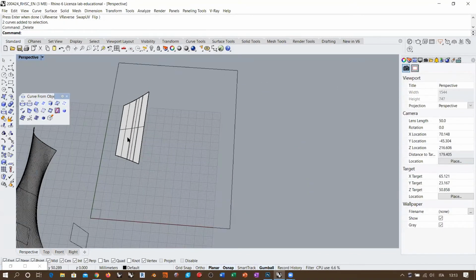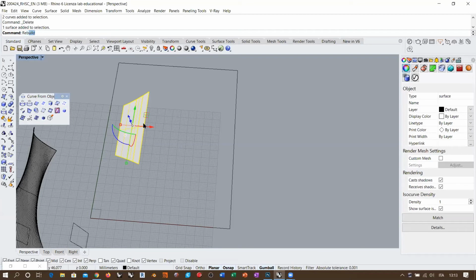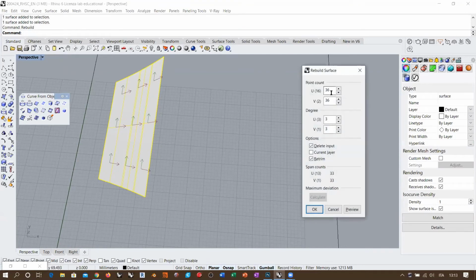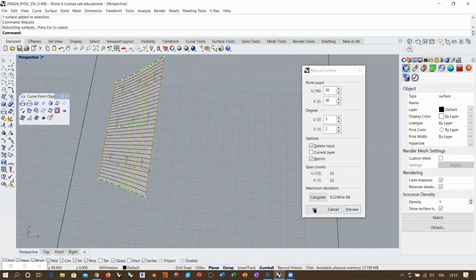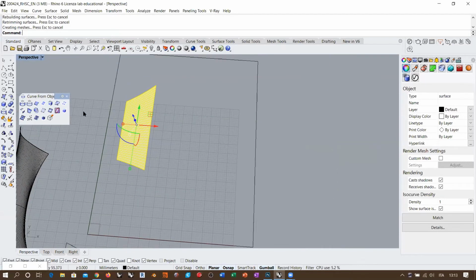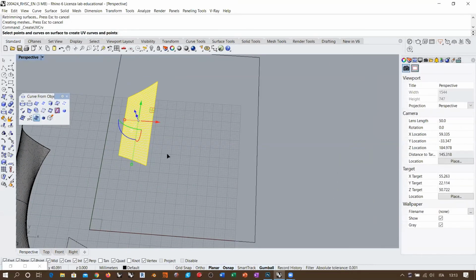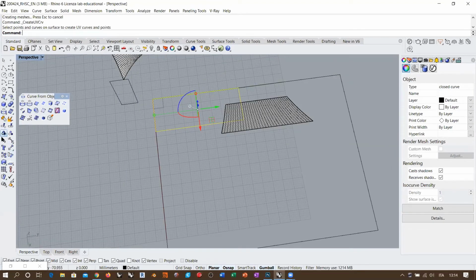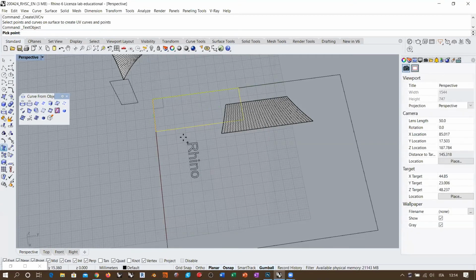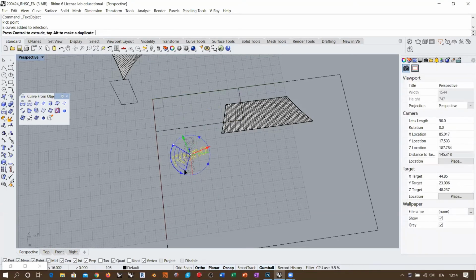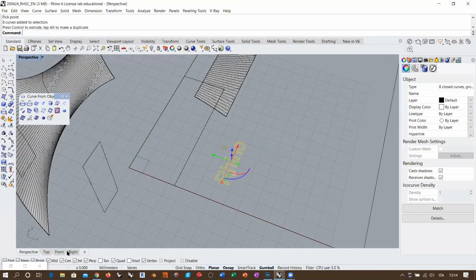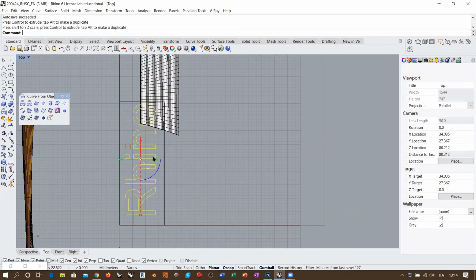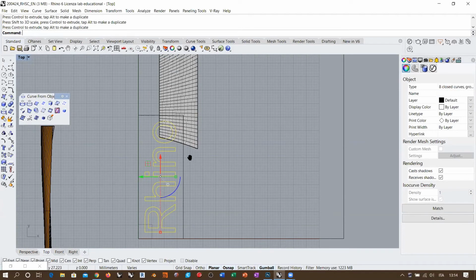Once I see this, I know that I can take this surface, rebuild it in order to avoid variation of speed in this direction. So I rebuild it using lots of control points, like this. I don't care. I have a regular topology. I make the UV curve of this thing, which is going to be this rectangle, and I'm going to apply my text, which is going to be original like Rhino, and take it, turn it 90-degree vertical, and then go into the top viewport, move it here, and scale it up, and place it more or less in the center, and I have this situation here.